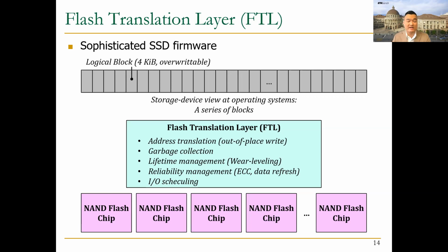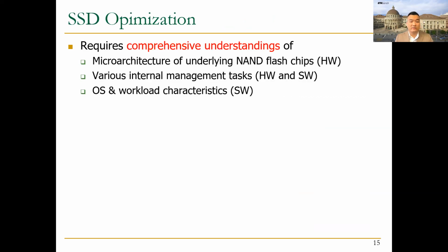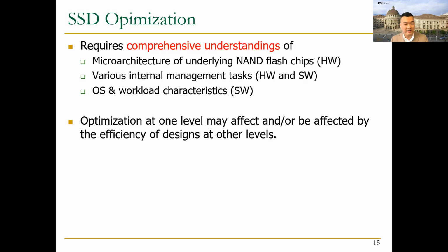And as you can imagine, all these tasks significantly affect the performance, lifetime, and reliability of the SSD. So there are many research topics there. So in order to optimize an SSD, one needs to comprehensively understand the design of underlying NAND flash chips, as well as various internal management tasks necessary at the FTL level, and OS and workload characteristics. And optimization at one level may affect or be affected by the efficiency of optimizations at other levels.